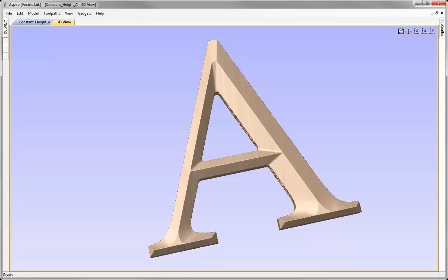I'm going to show you how to construct the spine of your letter or the center line of your geometry using the vector drawing tools. Then we'll examine how it's possible to very accurately position the cross sections for your 2-rail sweep to give us all the angles of the letter. And then finally we'll throw some quick toolpaths on this just to finish the part off.